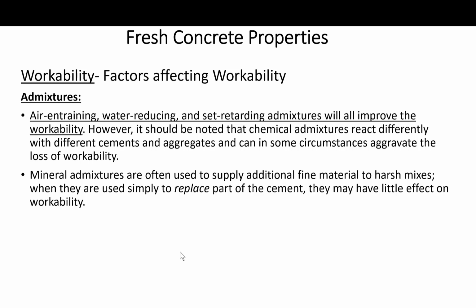But there's a big but here that you have to remember. It should be noted that chemical admixtures react differently with different cements and aggregates, and can, in some circumstances, aggravate the loss of workability. In particular, when using high quantities of superplasticizer, which is required for some high performance concrete mixes, the problem of cement plasticizer compatibility must be addressed.